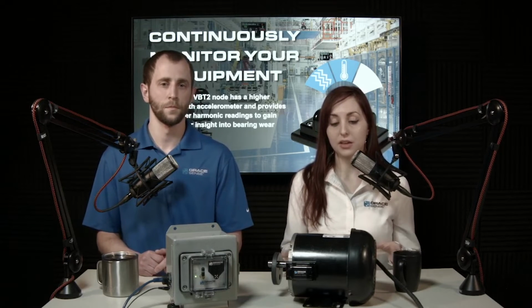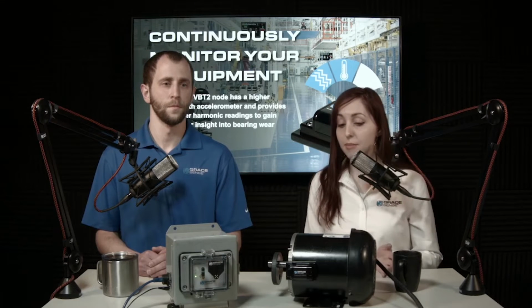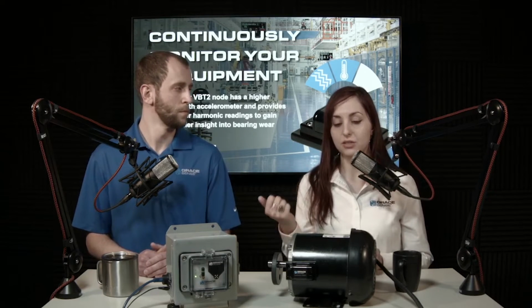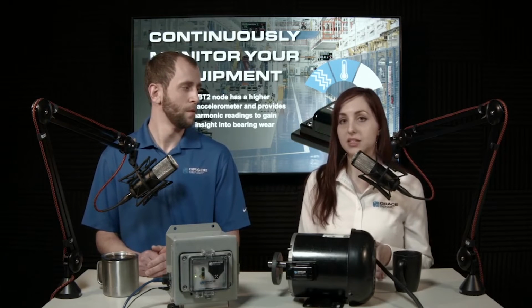So with that, let's go ahead and have Isabel introduce some vibration monitoring methods. Yeah, so there are several we want to list out. Starting with the most traditional method you might be familiar with, typically you have a maintenance schedule set up depending on the equipment you have and how critical it is. You might have, at most once a month, a technician that goes on site with a portable vibration test instrument and checks each individual machine. But most likely you have once-a-year-ish maintenance on most of your equipment. So that's the first basic method.